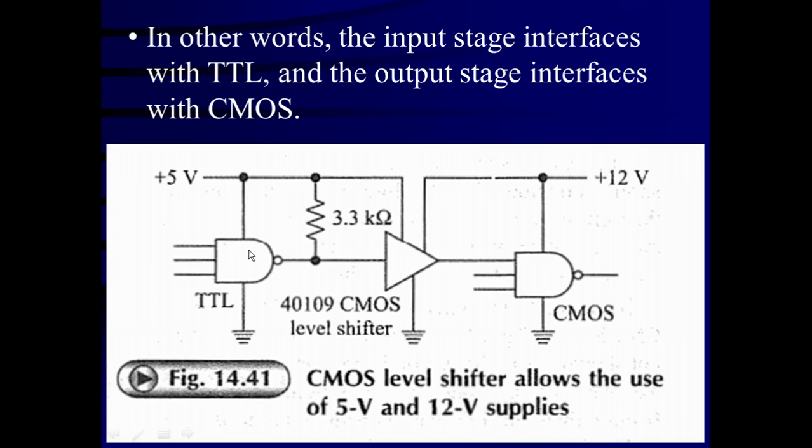When the TTL output is low, the output voltage can be any voltage from 0 to 0.4 volt. For this CMOS IC, 0 to 1.5 volt is allowable in the low state, so no problem.